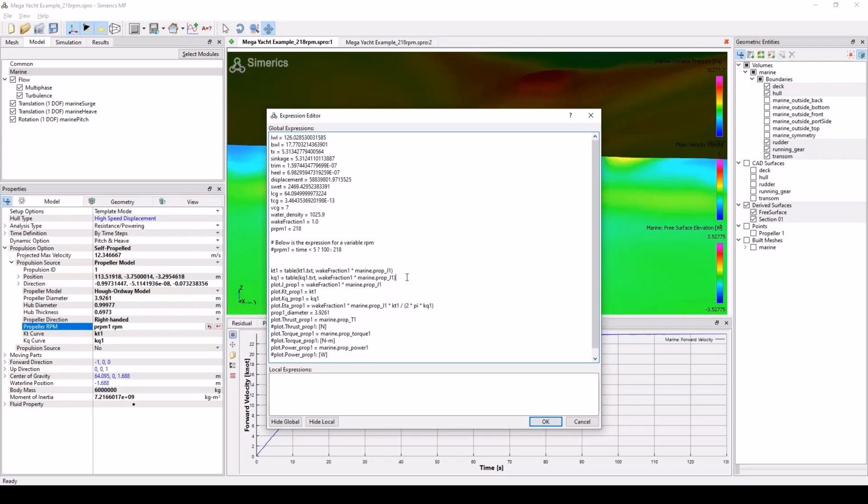What's interesting about those variables is that they're not defined in a normal way, like just a value or a simple expression. They use this keyword table. That expression table means these values of KT1 are defined elsewhere in a file in the form of a table that I'm going to look up. The name of the file is called kt1.txt. It's a text file.